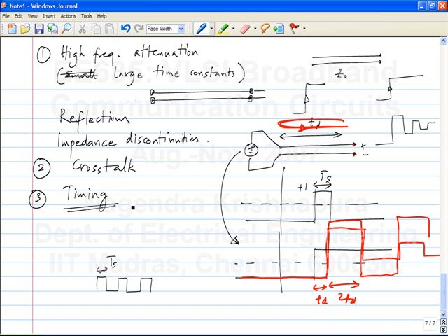That is, knowing the bit interval and also knowing where in the bit to sample, right? Not every place may be ideal. You may want to sample just before the transition, or at least you want to sample where the probability of error is the smallest. Okay, how do you find that? That is also a problem. Okay, we can discuss this a little more in the next class, but that is a big problem.